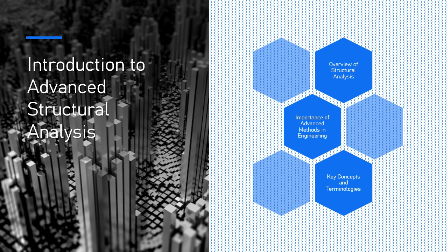In advanced methods like FEM, displacement calculations are performed at many points within the structure, nodal points in the case of FEM, which allows for a more detailed and precise analysis. Displacement analysis is key for assessing structural serviceability, ensuring that a structure does not deflect excessively or experience unintended movements.